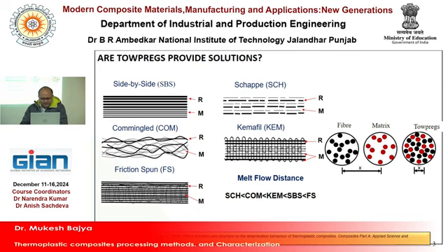But whenever you shift to the commingling process, the reinforcement materials and the matrix are mingled together. Whenever you make the composite from these materials, it will easily adhere all the reinforcement materials; all the filaments will stick together. That's why I told you commingling is the most important technique.